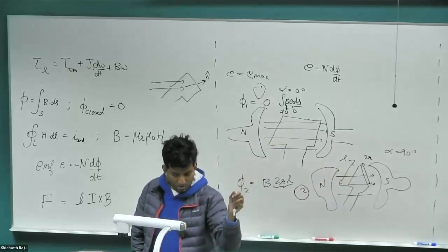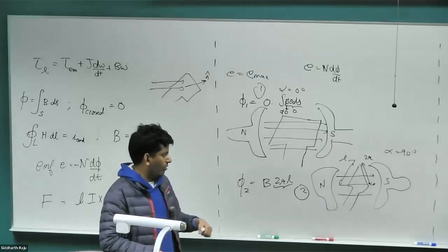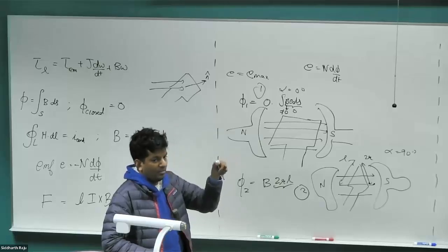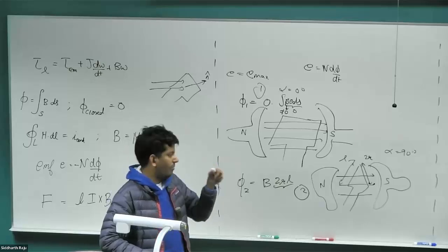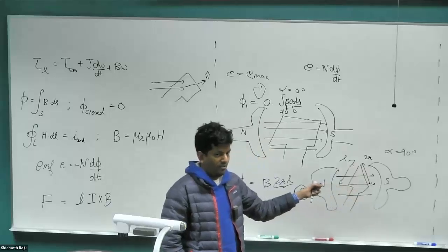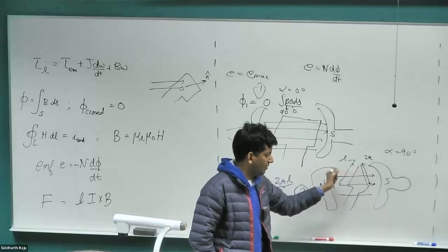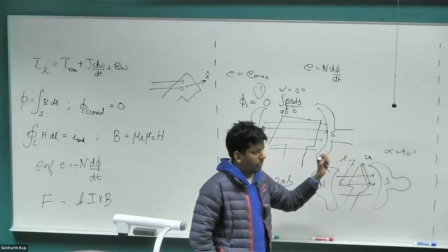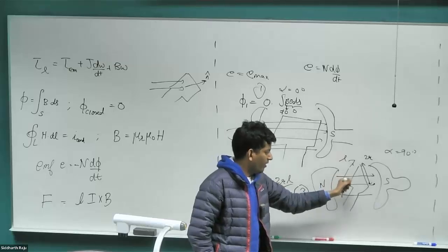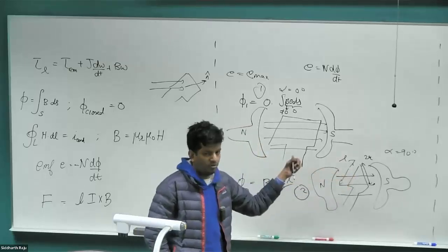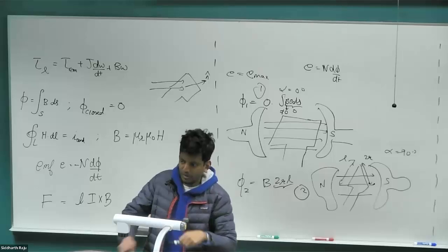So going back to the question Thomas had asked, of what would happen when the brushes are bigger than the commutator segment, we will end up shorting the winding for a short period of time. But the shorting happens when the conductor is at 90 degrees. At that point, the EMF is very close to 0. It won't be exactly 0 because the B field looks like this in our ideal case, but in reality it will get twisted around so that even at that location there will be a tiny amount of EMF, which we'll take a look at, called the armature reaction. But for an ideal case, at least the EMF is 0, so we can safely short the two windings externally. So the brush can be a little bit bigger than the copper segment. Anybody have any questions?